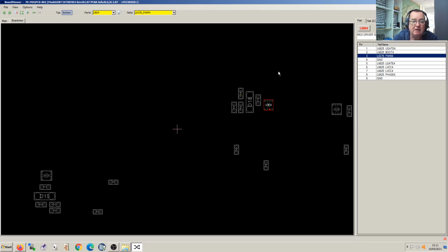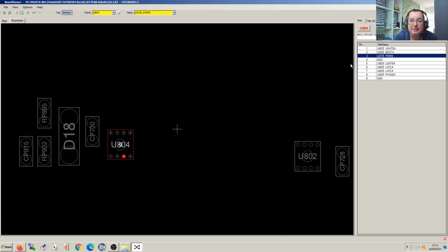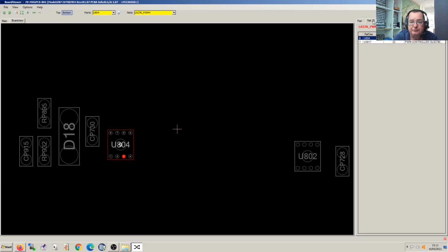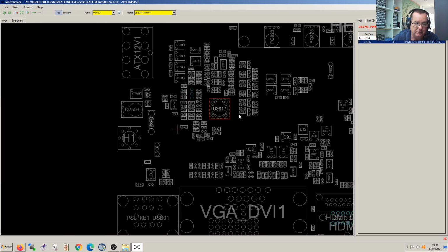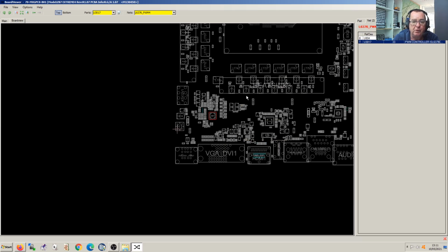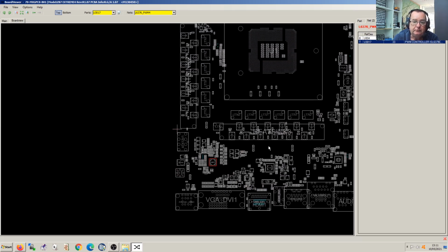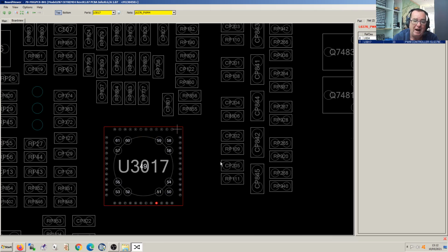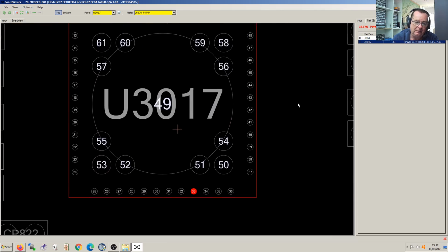It doesn't go anywhere else on this side, but net says 2. Okay, click on net, click to there. That's where it comes from. The controller. As we said when we started, we knew somehow that these VCore drivers, the MOSFETs, were connecting somehow to the controller. Now, not only do we know they connect somehow, we actually know how they connect.